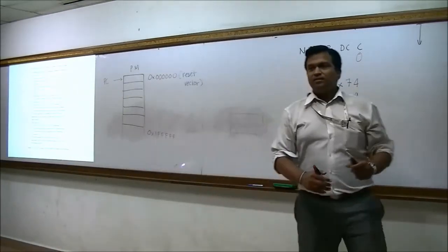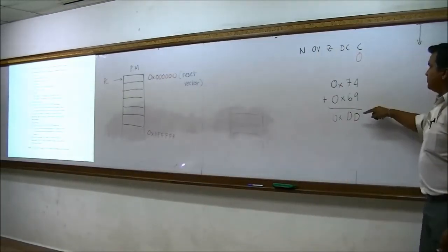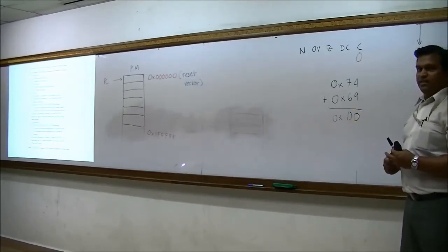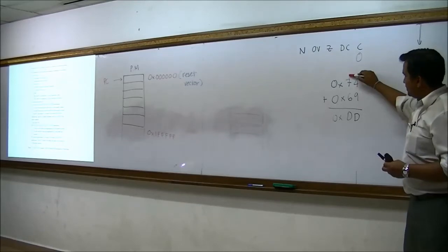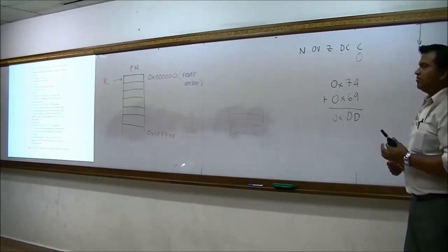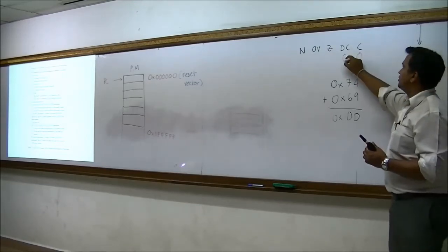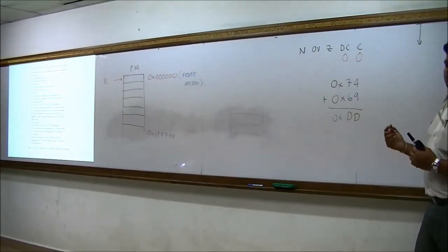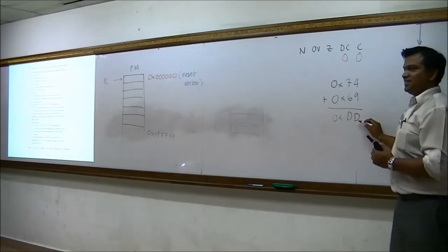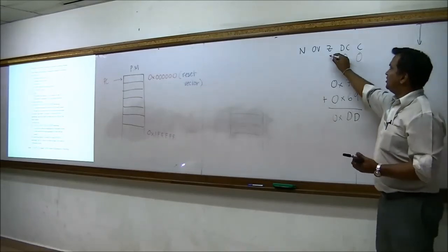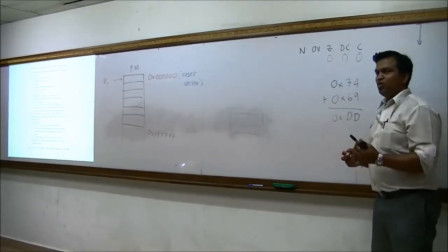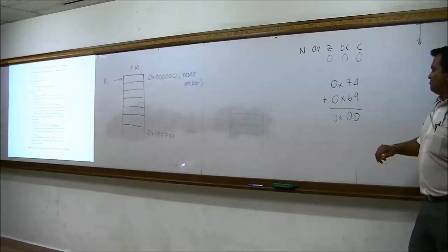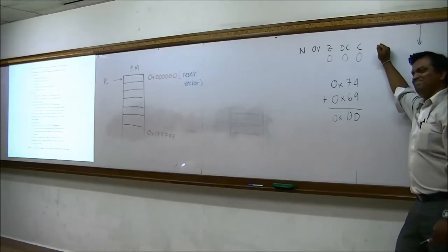Are you all following this? Yes. So the next question, do we have a digit carry? When we add this one, do we have a digit carry here? No, we don't have, so it will be 0. Is the answer 0? No. This one you have to be blind to make a mistake. The answer is definitely not 0, right? So the Z bit is 0. Do we have overflow? No. How do you know? There's no sign change.